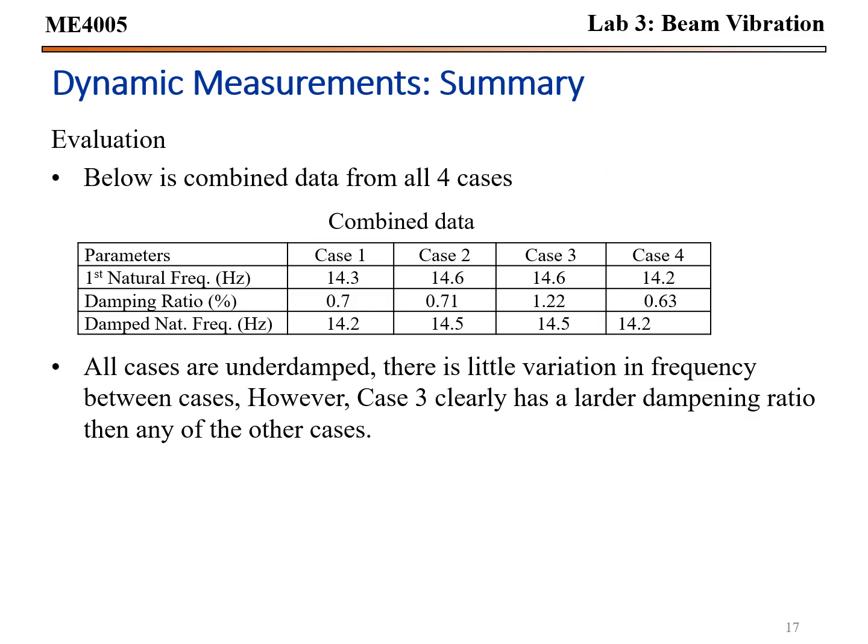Below is combined data from all 4 cases. All cases are underdamped. However, there is little variation in frequency between cases. Case 3, the one with the blue tape, clearly has a larger damping ratio than any of the other cases.